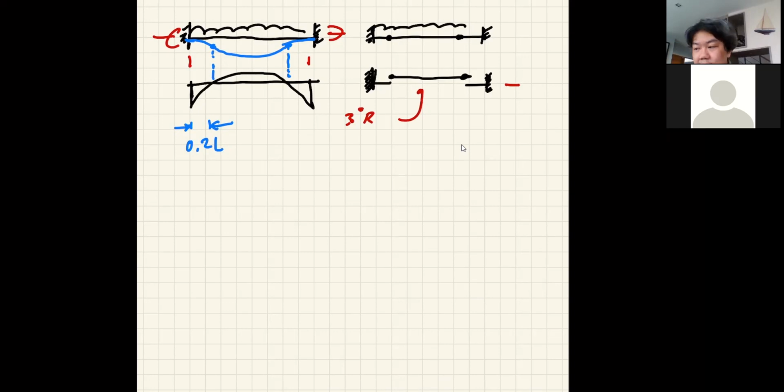Okay, so by doing that, you can easily solve the indeterminate structure just by adding the hinges to the locations where they should be. Now, generally, it's at the point 2, but in terms of approximation, they would say whenever you have the continuous beam, the location where you should add the hinge should be about 10% of the length, just to be safe. Okay, and we are talking about the vertical load now.